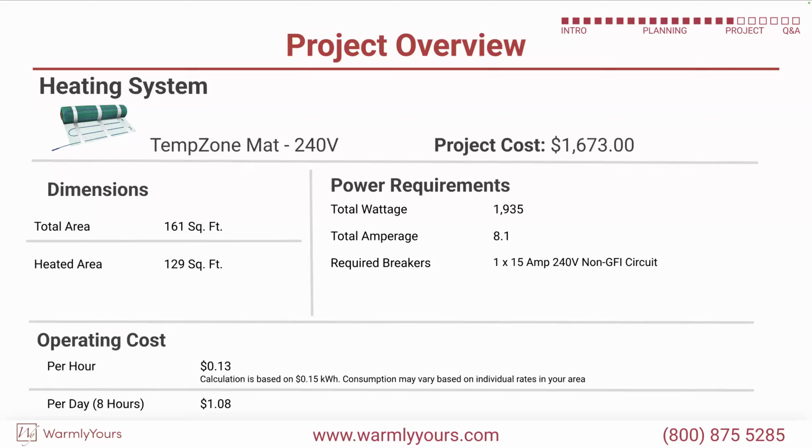It's the same thing with, and Mary can talk about this, large installations where we do a thermostat and a power module because it's over 15 amps. Each control can handle 15 amps. Now, if you have two small cables attached to a thermostat, that's cool as long as they're less than 15 amps.